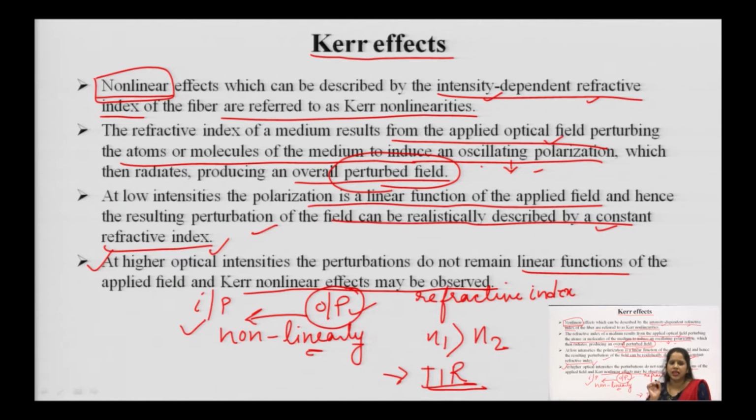So, we can easily say at this particular instant that if we want to reduce the Kerr effect in any sort of optical fiber propagation, then we have to maintain the intensity of the optical light low. We must not increase the intensity of optical light, because the effect is most prominent at a higher intensity. At low intensity, its value is relatively negligible, or we can say low.